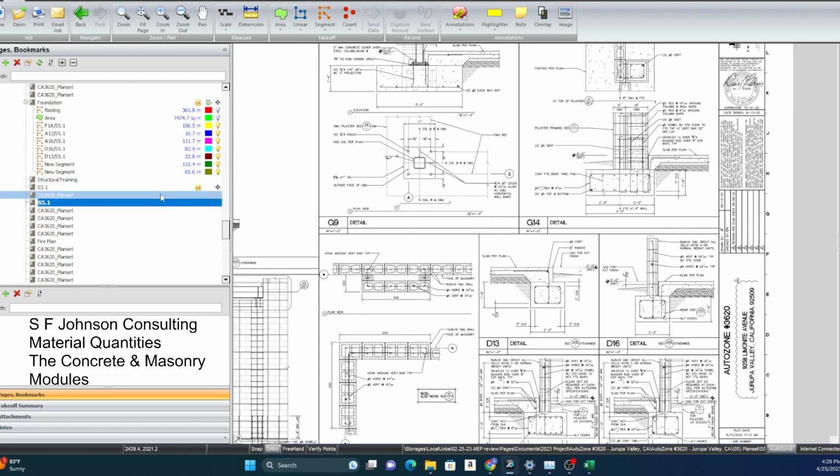We're going to have material quantities for each of the trays. Now this is just for what we just did, a foundation, and concrete, getting the cubic yards together. We have to do the same thing for framing: how many studs do we need? We'll do that. For the masonry walls, how many bricks you need? If you know the size of your wall and the size of your bricks, you can price it by brick, by square foot, or by linear foot.